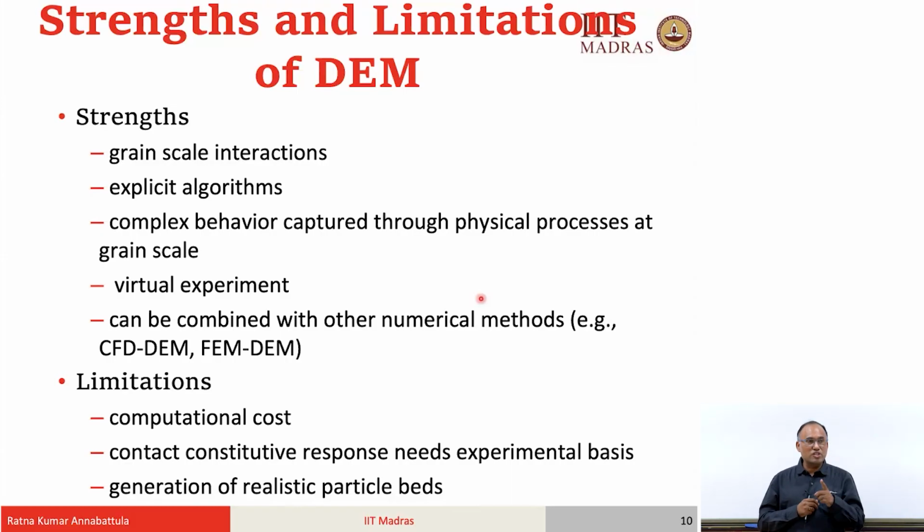Although there is an issue: if you do not use the right time step, you might actually be getting a wrong answer. You need to ensure that you have a sufficiently small time step. Okay? And it can capture the complex behavior through physical processes that happen at the grain scale.